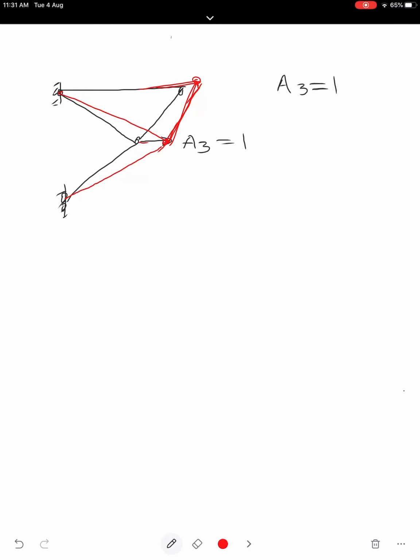Actually, all of you have gone through the theory of structures course, the virtual work principle and the energy principle, where in trusses we have calculated displacements at every joint. So only after calculation will we come to know, depending on the loading condition and the magnitude of the loading, whether this joint will displace or not. So we are assuming that if you pull it horizontally, there is one possibility that it might displace in the horizontal direction.